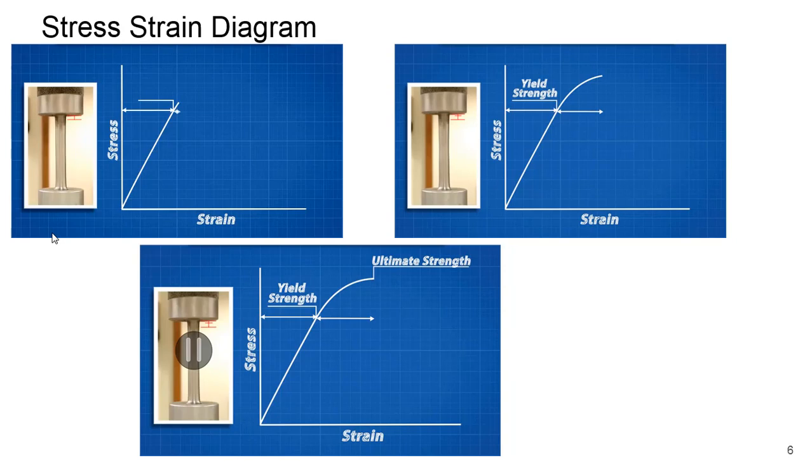For the ductile materials, failure means plastic deformation. So to avoid plastic deformation, we always keep our design such that because of loading, the stress that is developed within the component should be in this region. And you can see that this point is called the yield point, and the corresponding strength is called the yield strength. So up to this point we will consider the material to be elastic. This is the consideration by the material science engineers.